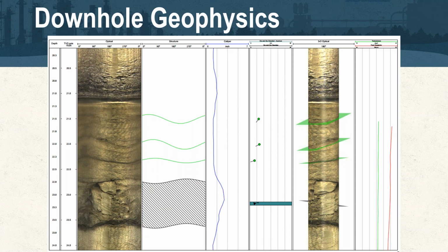But even those best efforts can be thwarted in the field, whether it's over time or just degradation. Recently we did a site here in Pennsylvania where the borehole had only been installed about 6-8 weeks before we went out there. Because of some high angle interconnected fractures, there was significant natural spalling on the inside of that borehole. So we definitely had to take that into account. It didn't preclude us from analyzing that zone, but that could be a consideration, is the aging in some of these softer, less competent materials.